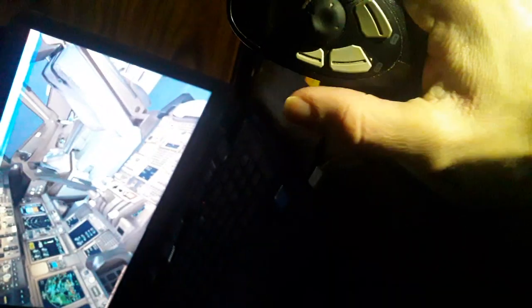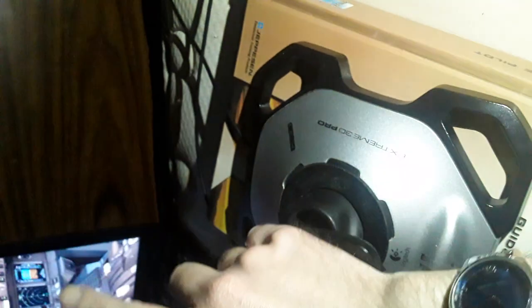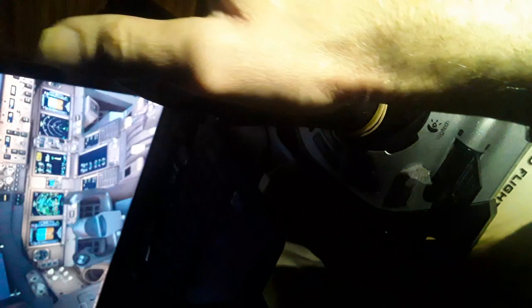You can see I can pitch up and pitch down. You can see the control column, the yoke of the Boeing 777. And the control, we can bank roll left and bank roll right. You have proportional side stick deflection and yoke deflection. So you can leave it neutral, you can also pitch trim. You can make small adjustments if you need. You don't have to move it too much.